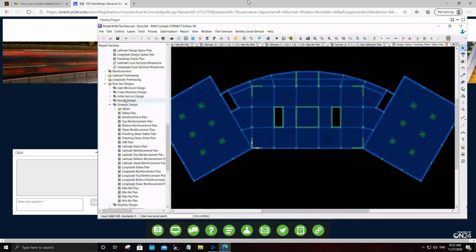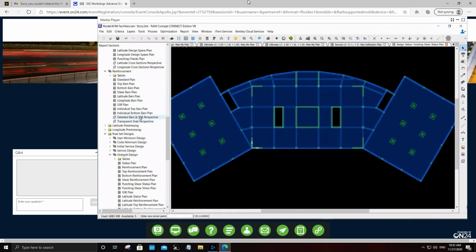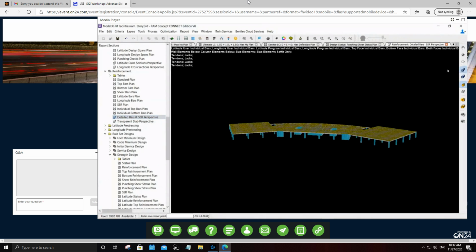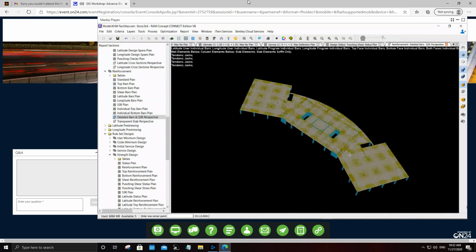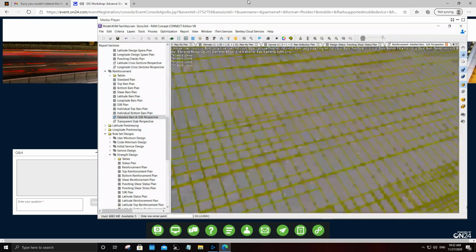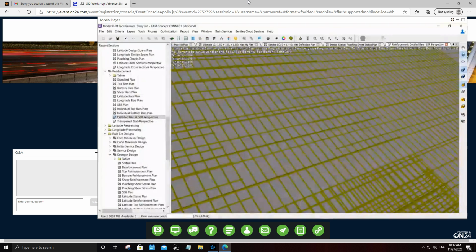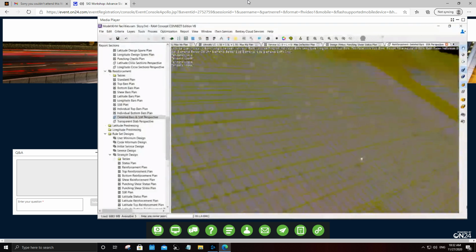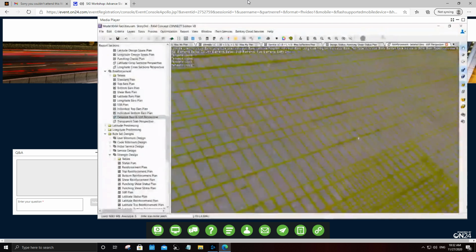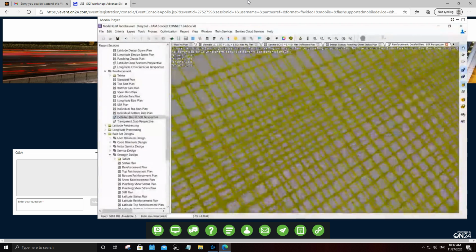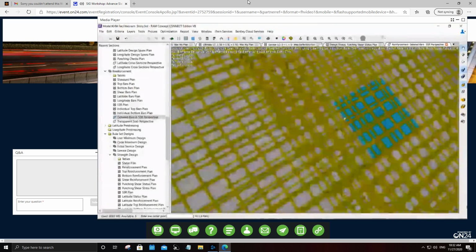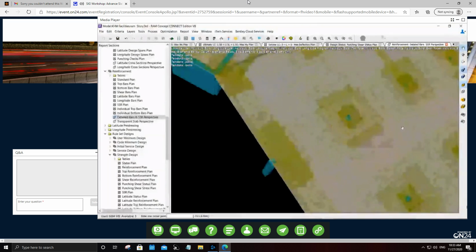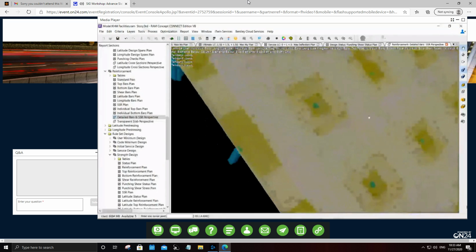Now, as I said, let's look at the reinforcement, and let's go through the detailed 3D view that the program has generated for us. The program can generate the 3D rebars for you, and fortunately, you can even export this to any program which is available for editing, or let's say modifying as per your standards. Here you can see a case where there is a drop cap, and the program actually gives very good reinforcement around that particular column.